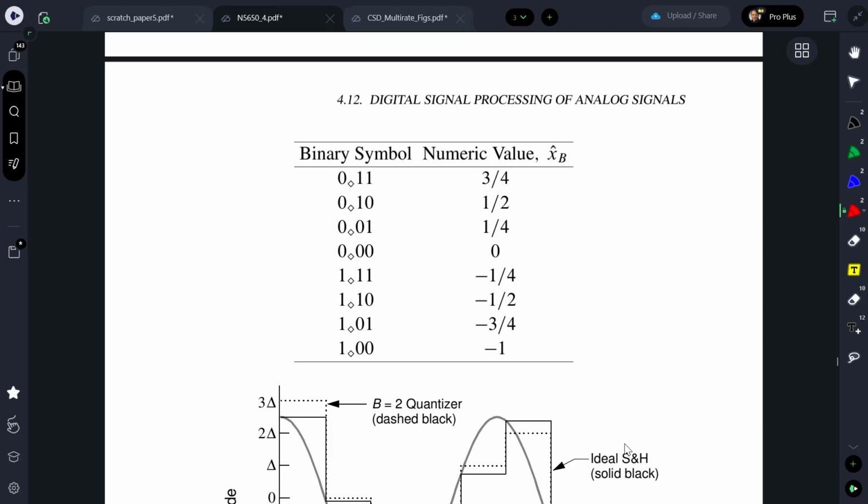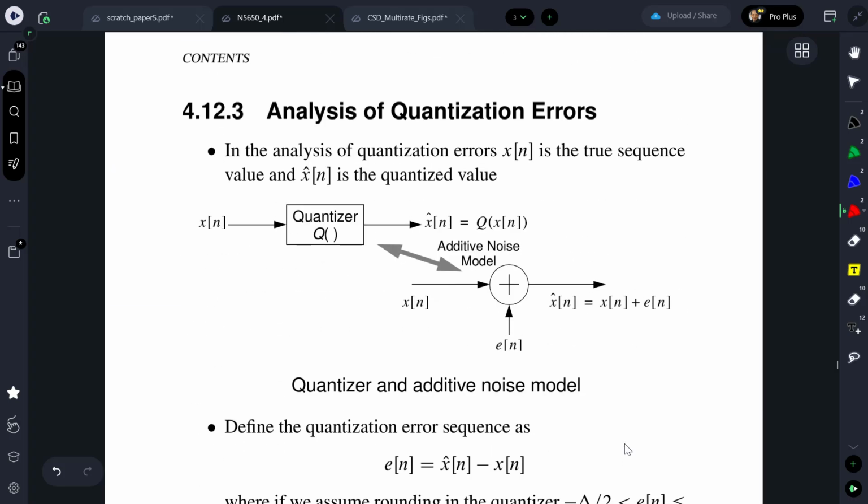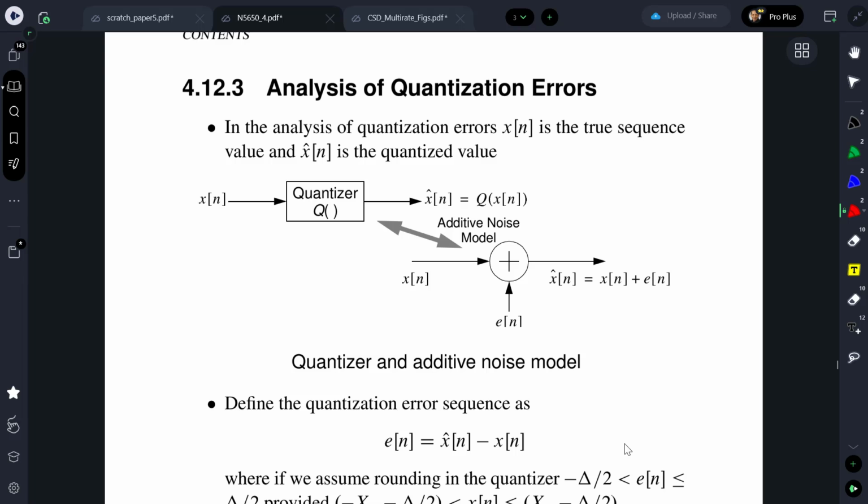We model the quantizing operation very simplistically. Rather than the actual quantization, we want to model it mathematically on pencil and paper effectively, and we model it as an additive noise model. This is subject to argument, and it's based on a long-standing simplification, though, that you just model this, not run a simulation. We're just going to treat the output of the quantizer as if it's the true input plus additive noise. And this additive noise is uniformly distributed over the quantization step, half below and half above.